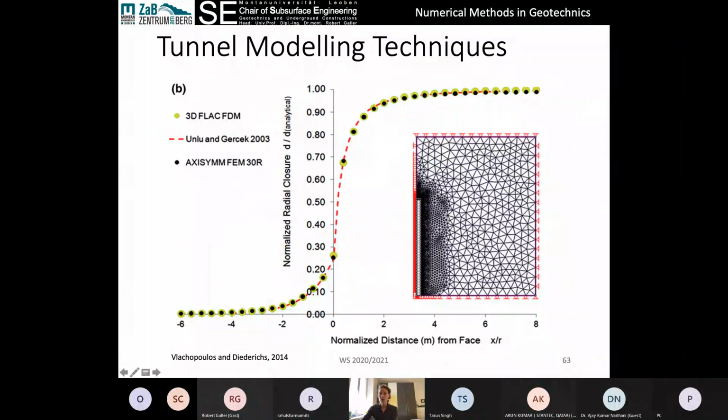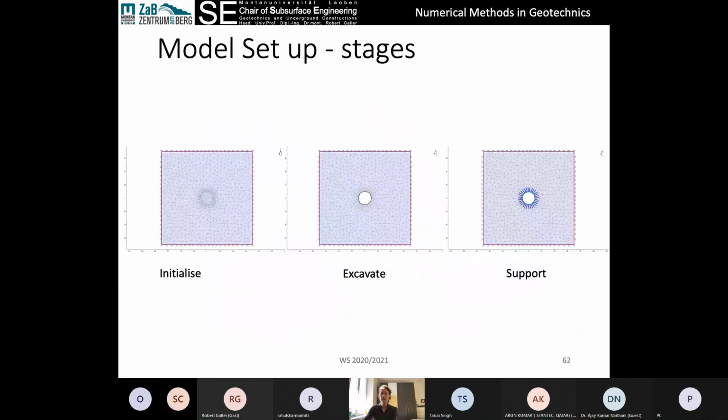That's not actually how we construct a tunnel. When we construct a tunnel, we do an excavation. We take maybe 1 meter, 1.5, 3 meters, however good our rock mass is. We take a certain amount of material out and then we support. So if we're applying our support somewhere up here, that means we're applying our support when we've only had maybe 60 or 70% of our deformation. From what this is saying here, 100% of our deformation has happened, and then we apply our support.